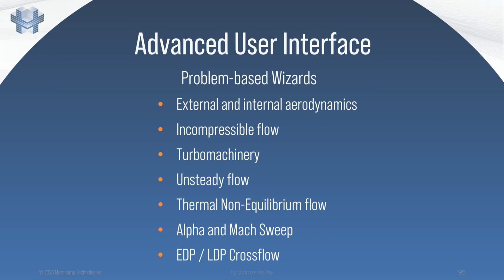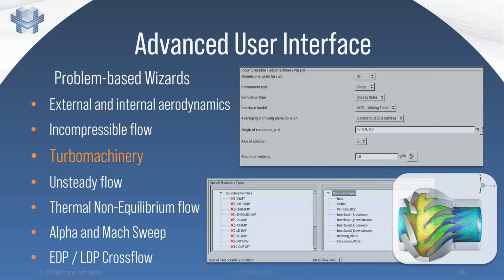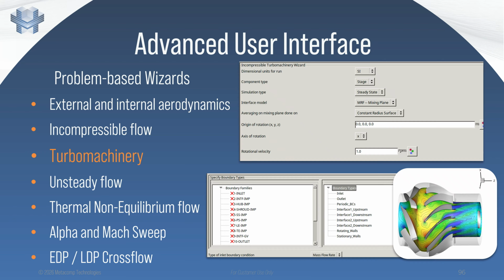Specialized wizards are available to automate the setup for specific problem classes. The setup incorporates best practice knowledge gained from years of experience and deep theoretical background. As an example, the turbomachinery wizard automatically sets up the initial and boundary conditions along with the numerical and post-processing settings specific to turbomachinery problems.